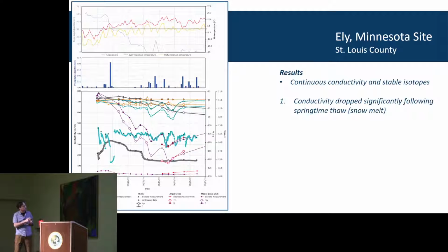You can collect time series data of stable isotopes. For instance here, these deep declines in stable isotopes are for the 2 creeks on site. Up here you have snowpack, so there was 63 centimeters of snowpack, and then starting in late March, the snowpack's basically declining. So we're melting snow, and sure enough, as you would expect, you're getting a lighter isotope signature in these surface water features. But for a couple of the target wells, we start to see a lighter isotopic signature in stable isotopes as well. So that's one point.